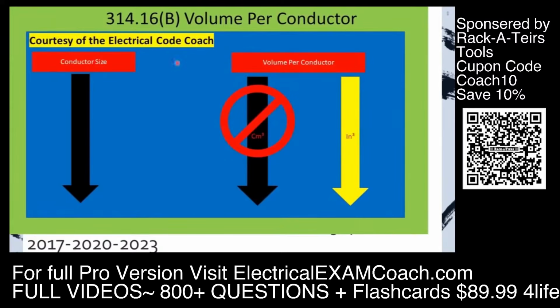On the left-hand side is our conductor size, and on the far right-hand side is going to be our cubic inch volume. Every box can only handle so many wires and devices, and that's what we're going to learn in this lesson here today. Each box has so many cubic inches that you can fill, and each conductor and device takes up so many cubic inches of that box. Now, let's do some practice questions and get to it.